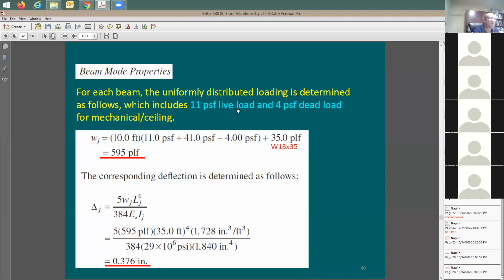So in what case do you amplify the loads and use these load factors? When you're testing strength, right? So this is not a strength check. What would you call this kind of check? Serviceability. In serviceability, you just use the loads as is, like when you do deflection analysis, which you just mentioned a minute ago. So this is the reason. Yeah, that's right. All right, thanks, Ben.